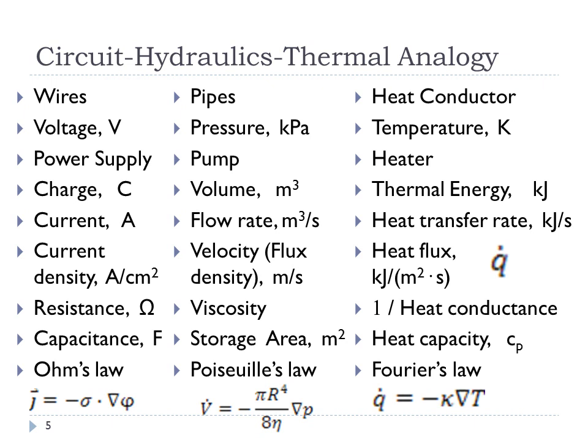In this course, we're not going to be covering dynamics, where the capacitance storage, or the heat capacity of a heat conductor, is important, but I just wanted to point out that there is an analogy in all three of these cases. And then the microscopic form of heat conduction is called Fourier's law, which says that the heat flux is equal to negative the thermal conductivity times the gradient in temperature.